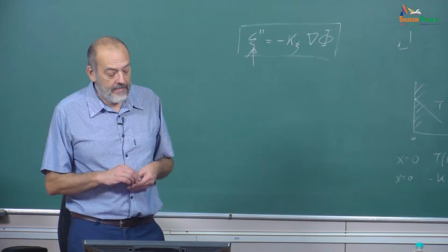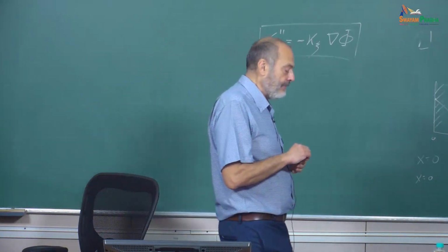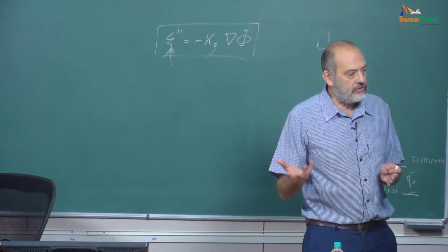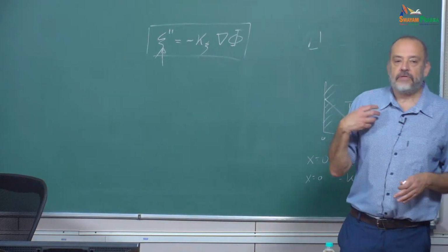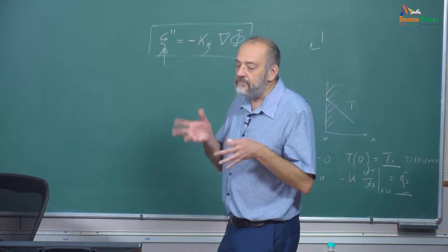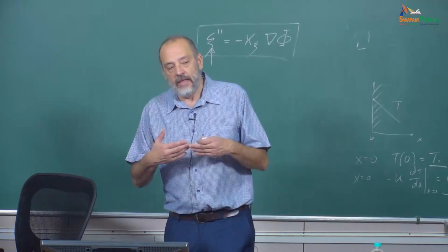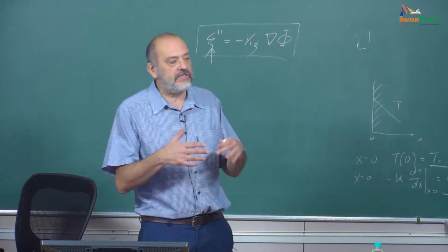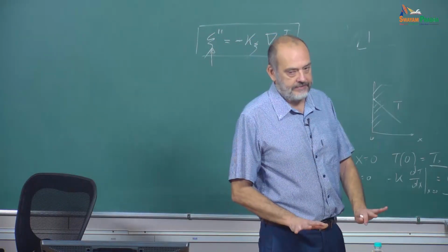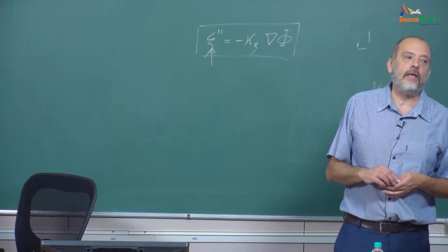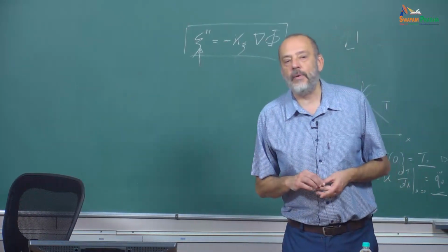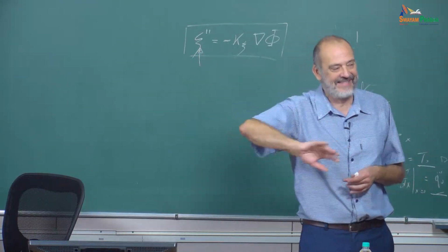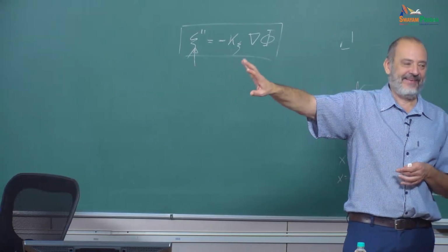Why is the Reynolds number so important? Because there are criteria saying that above a given Reynolds number, the inertia is dominating. So the viscosity is somehow less important, and it is not able to dissipate the energy at the various scales. We are entering now the domain of turbulent fluid mechanics, which is again another course. So I cannot do it, okay?